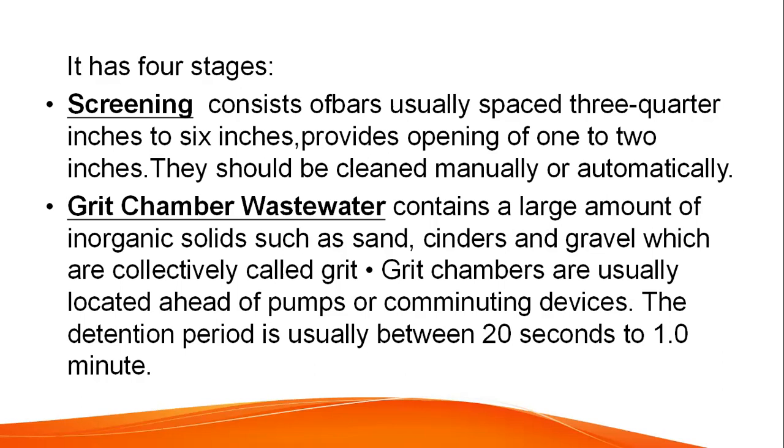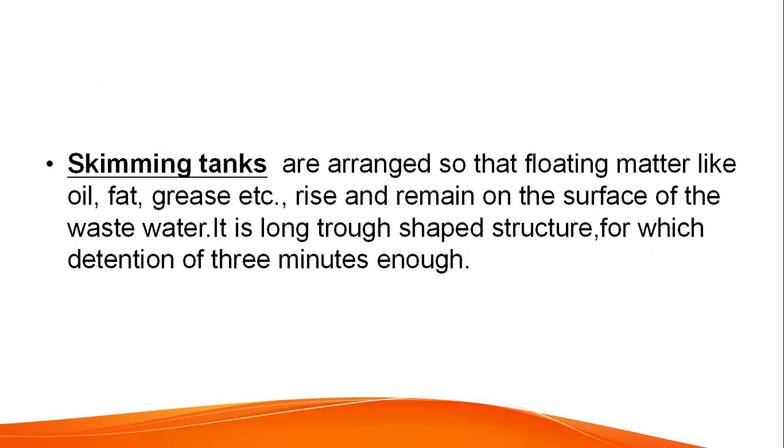So the grit chamber removes the inorganic solids. The main point is that it protects the plant from this sort of inorganic solid, which can clog the operation plant. So moving towards the next slide and knowing what is the third process, skimming tanks.